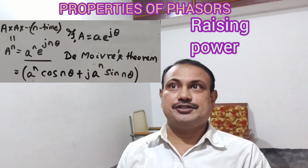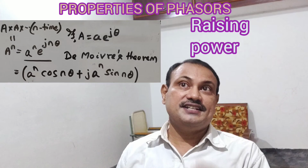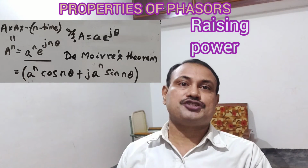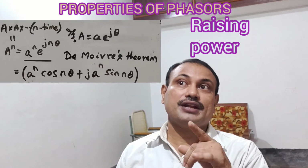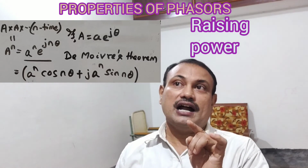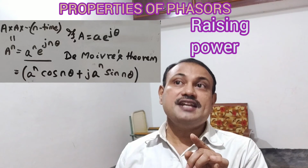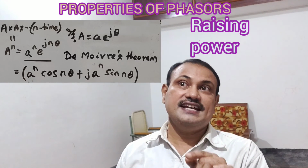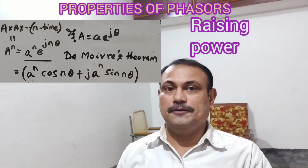Raising to a power of phasors: if we multiply a phasor n times, then the resulting phasor can be expressed in accordance with de Moivre's theorem, which can be written as A^n equal to a to the power n as the amplitude part, and e to the power j times n theta, which can be extended as a to the power n times cos n theta plus j times a to the power n sin n theta by de Moivre's theorem.